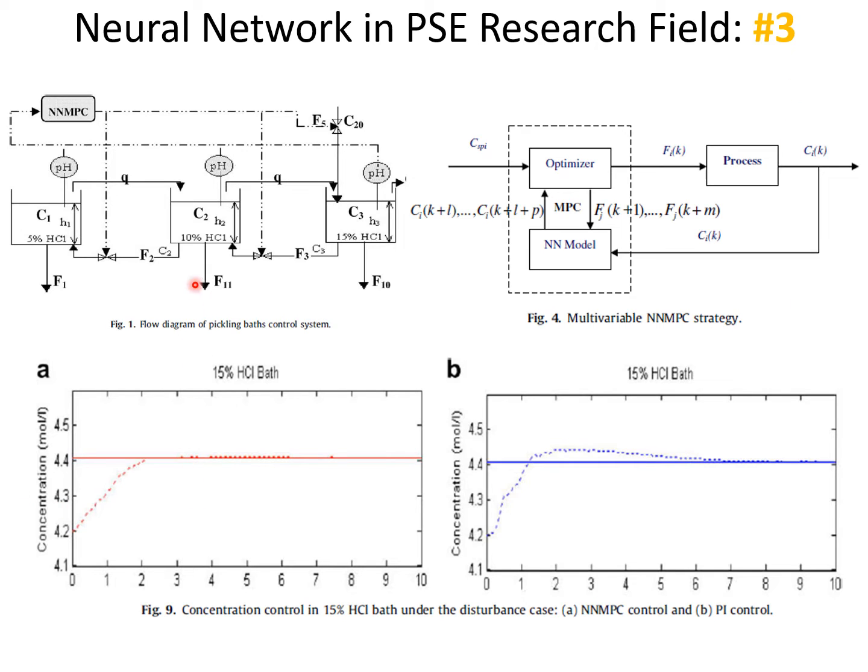So we use it. He just tested it for all the basic set point, regulatory, and so on. I'll just show one result here for concentration change. It goes right into the concentration that we want from some other values. Okay, very closely controlled with very little disturbances, very little offsets, very fast control in this system. Compared to the PI control, we can see the PI control overshoots, takes some time to reach, and things like that. Okay, this is just one example.